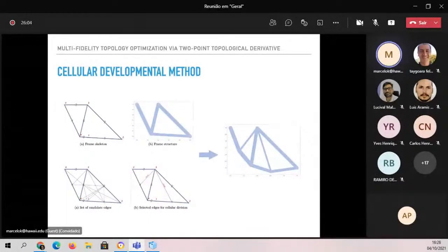And you notice that it looks like one is missing on the triangle, that inverted triangle on the left. But the reason that candidate's not there is that I can control manufacturing parameters to decide whether I want to add another member or not. And in that case, I had a minimum constraint on the angle that the new member can make with the existing members. And that's why you don't see one of the members there, because that would violate that constraint.